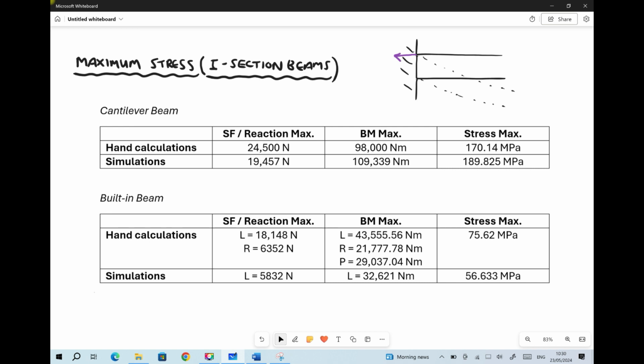And at the bottom edge of the support, we see that the beam is being compressed against the support. So the reaction force is going to aim to push away against the bottom face of the beam. If we think of the impact that has on the opposite end of the beam, these two forces working in tandem are going to cause a turning moment.